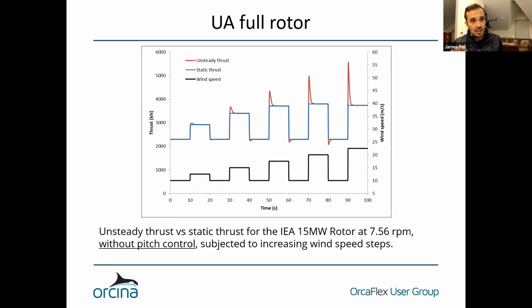This is a pitch regulated turbine, as most of them are, as opposed to stall regulated. The whole idea is that if you were running the controller and the wind speed increases, the turbine wants to pitch the blades out and reduce the angle of attack to keep it out of stall. And if it doesn't go into stall, then these effects aren't so pronounced.